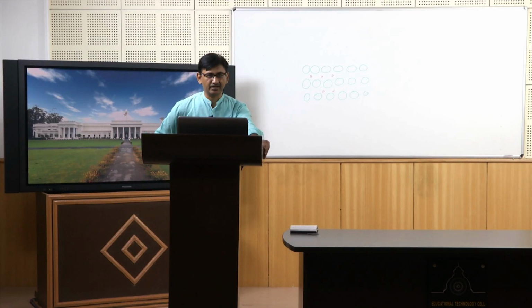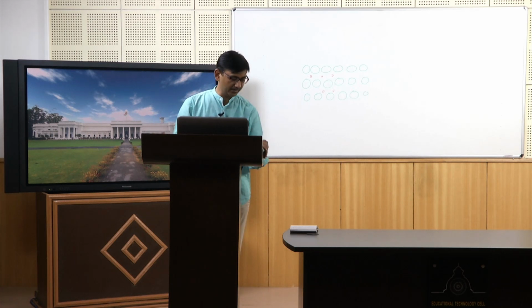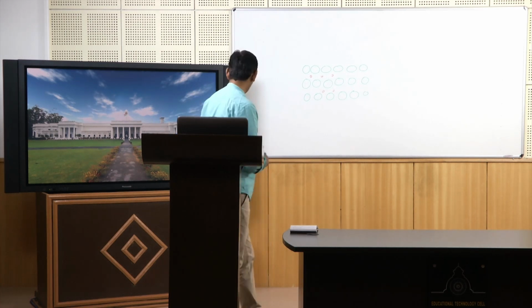So, the concentration gradient has to be very small to take this assumption. So, we are dealing with very dilute alloys. If we do that, then we can say that B atoms have equal probability of jumping to a neighboring vacant interstitial site. If all the neighboring sites are empty, then this atom can jump to any site, and the probability is the same. From there we will start the derivation for Fick's first law.